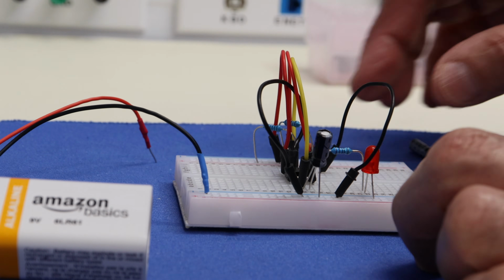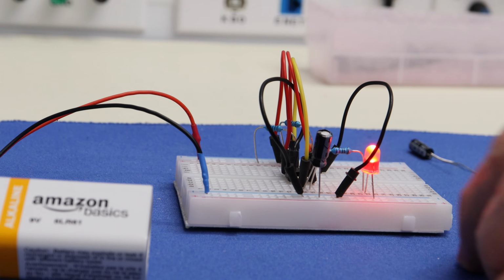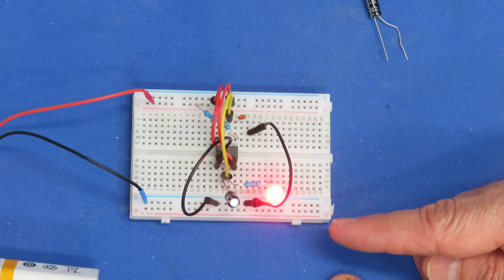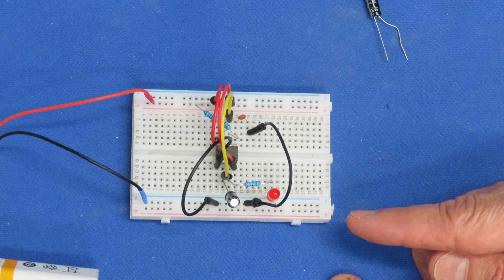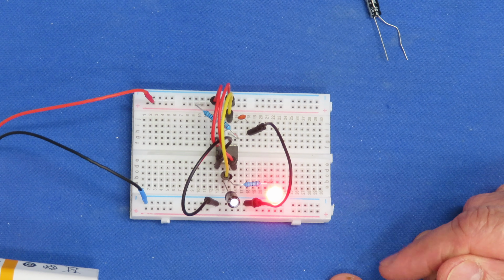Make sure I connect that correctly. And we'll power that back up. Now I've got a 22 microfarad. And as you may have expected, the period has changed. It's about twice as long, and that makes sense because the capacitor value is about twice as big. So it's taking longer to charge up this capacitor than it did the 10 microfarad capacitor. And so that's how we can change the frequency, or in this case, the blink rate of the LED. So here we have it, our first demonstration with the 555 in astable mode.